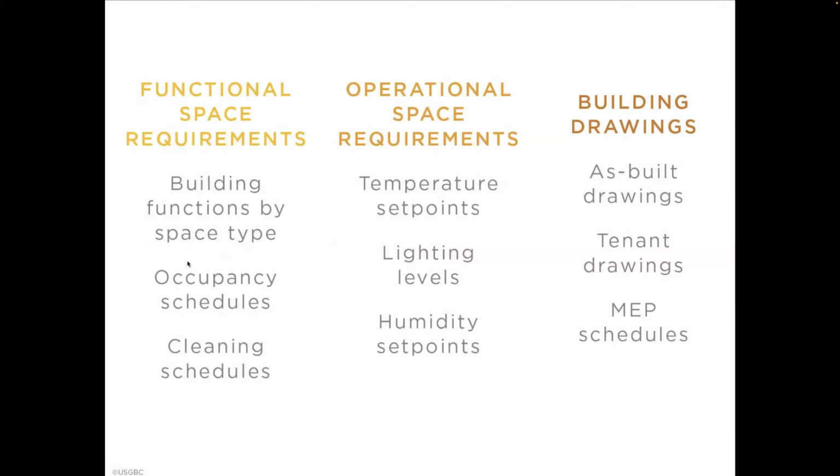All right, so what is the function? What are the schedules? What are the cleaning schedules? What are the set points, lighting levels, humidity set points? All these things have to be identified. And a lot of times, especially at the very beginning, they may not know what the set points are. They thought they knew what the set points were, and they go, wow, we should heat to 68 and cool to 78, and that's not where it is.